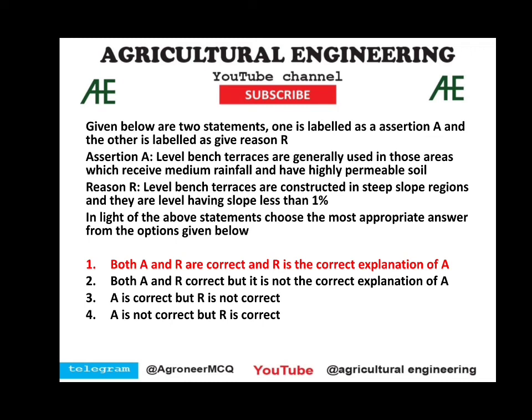Level bench terraces are generally used in those areas which receive medium rainfall and have highly permeable soil. This one is correct. Level bench terraces are constructed in steep slope regions and they are level having slope less than 1%. So both statements A and R are correct, and R is the correct explanation of A.